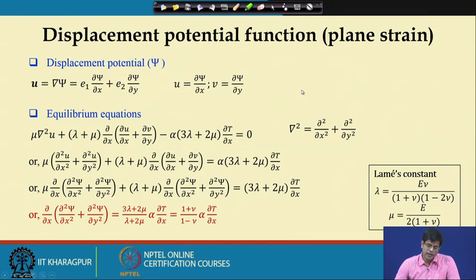Now, here we have followed the stress function approach in case of a plane stress problem, and then we can also form the displacement function approach or displacement potential approach in the plane stress problem.